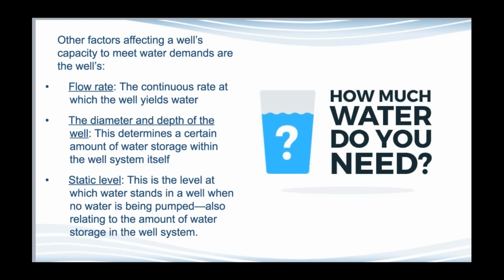An artesian is where you actually have pressure. It's kind of like where your formation is down at 200 feet, but your water level comes all the way up to 12 feet. That's considered to be an artesian because the actual aquifer has pressure against it, and that pressure is going to push that static level up to a specific level where it's going to sit within that well or within that straw. That is your static level.